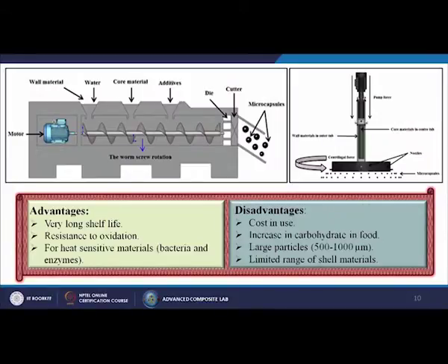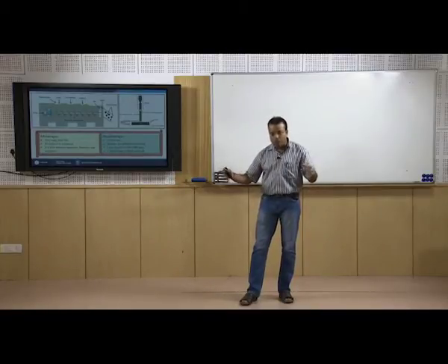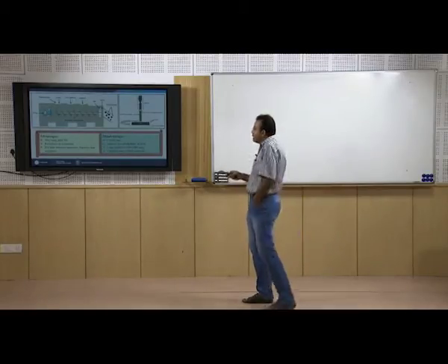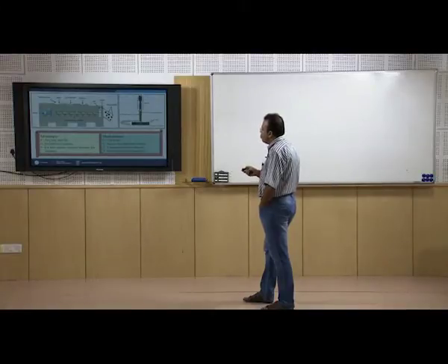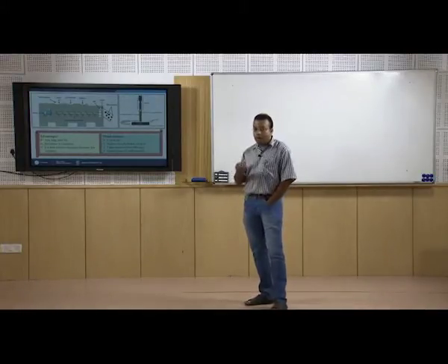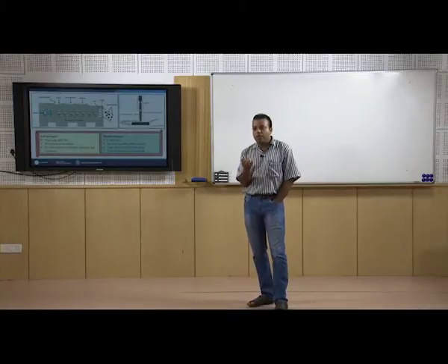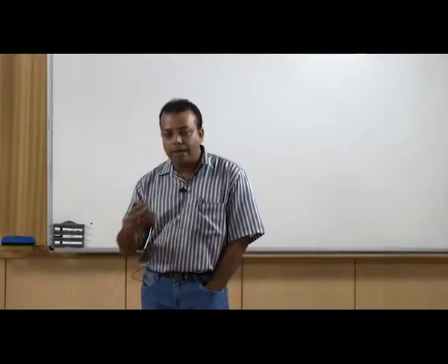By centrifugal action all the particles will come outside in a rod form, and then due to surface energy it is divided into small particles, or we may have some cutters by which we can cut that continuous rod shape into small particles. Then we get the material in which the inside is your core material and the outside is your shell material, or the coating material.